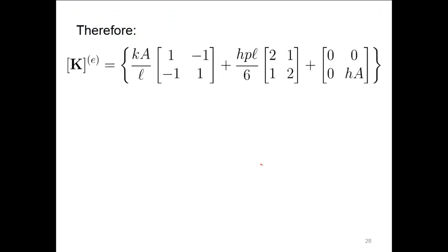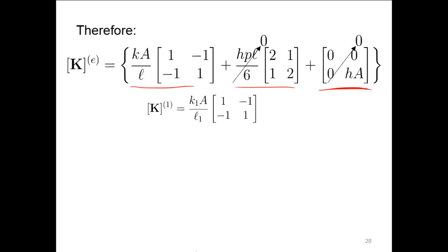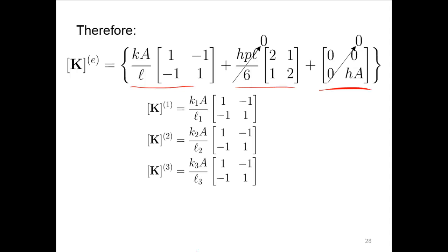All right, so here's the general form of the stiffness matrix for a thermal case. We have the conduction, we have convection from the outer surfaces, which in the fin case was the horizontal surfaces, and then the convection at the tip. In this case, we're in a plane wall, so we don't have to worry about either of those terms for the first 3 elements, elements 1, 2, and 3.